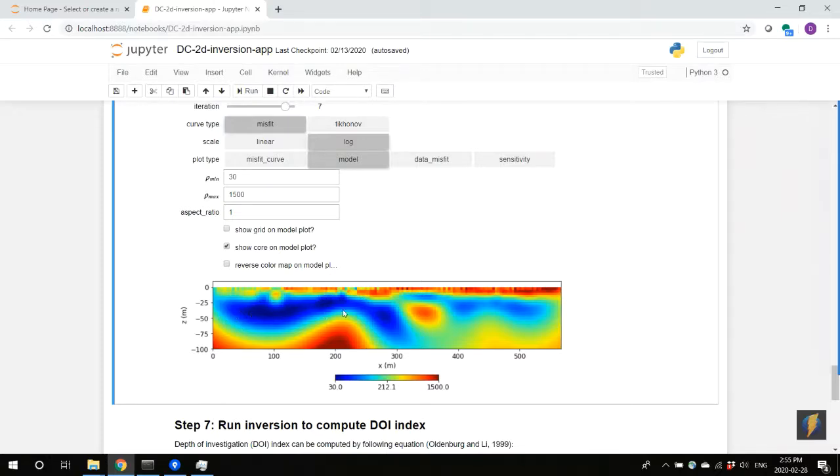So we know that there is this area of low resistivity here, and we know that it is highly resistive near the surface, but we don't really know what is the depth to this low resistivity region. It seems to be anywhere between 25 and even 50 meters. So this is a very broad, not very detailed recovered model. Maybe we get a general understanding of what is under the Earth, but we are maybe not ready to make